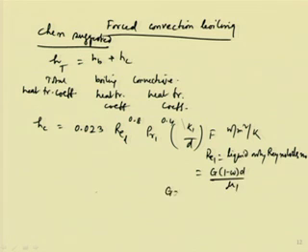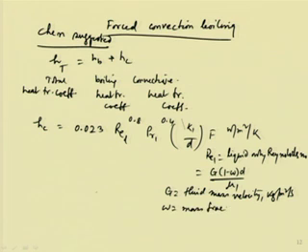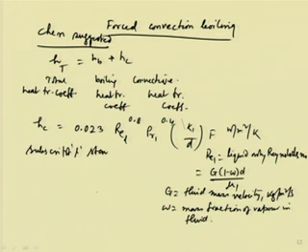Here G is the fluid mass velocity, which is basically kg per meter square per second, which may have the vapor component in it. So, w is called the mass fraction of vapor in the fluid, okay, and the subscript L stands for liquid.